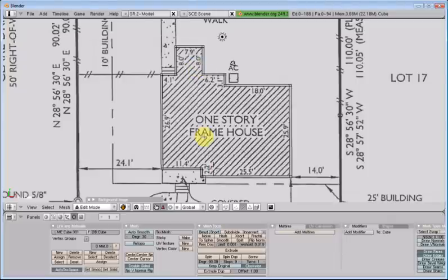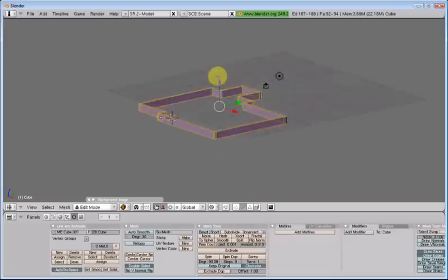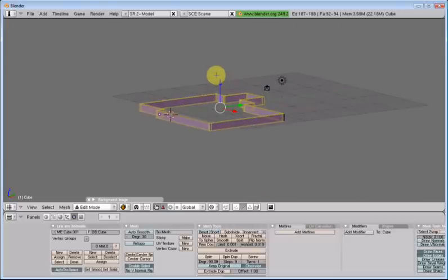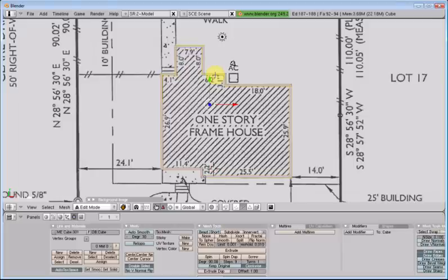So in our top view, what we'll do is hit B twice, B for boy, so we'll hit BB. And that gives us this, and then we can just go through and basically paint to select all our edges. Make sure they're all selected. And then rotate. Oh, actually, I screwed that up. Let's go back to top view, hit A, deselect everything.